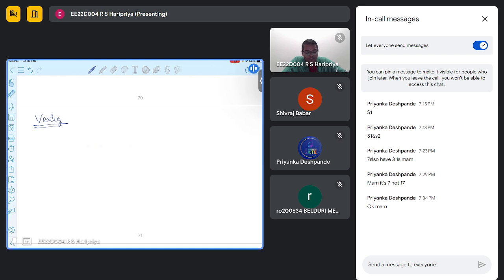So in Verilog, we write code to synthesize it to logic, like we can have a gate level, we synthesize to a gate level circuit. We have code which is used for testing purposes, and we call it a test bench. And the code which we write for the logic, we start with the module and we define the input and the output port. Say A is an input, B is an output, and every module ends with an endmodule, and we have various types of modeling like behavioral, and we will discuss that next week.